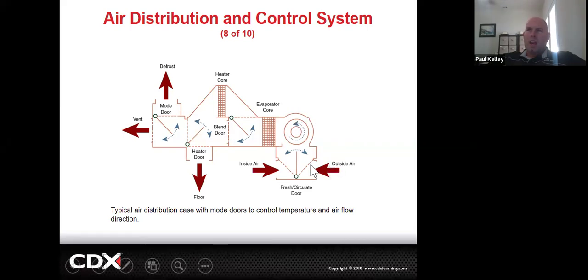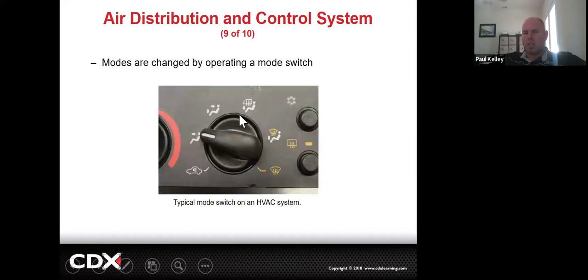All right, so just air would be air running through the evaporator core, but the evaporator is not cool. How would you make it air conditioning? You saw this when we did our work last week. How do we make that thing icy cold? Compressor, TXV is running, right? The air conditioning refrigerant cycle is going to work to actually get that lower than ambient. Totally understood it, right? Good. And then the mode door is going to control where the air actually discharges. Cool. Not exactly rocket science.